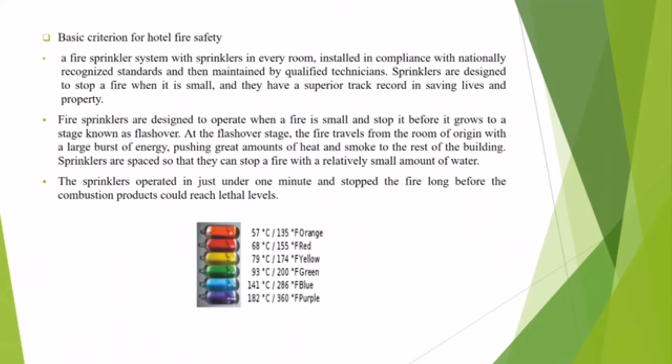Basic criterion for hotel fire safety. A fire sprinkler system with sprinklers in every room, installed in compliance with nationally recognized standards and then maintained by qualified technicians. Sprinklers are designed to stop a fire when it is small, and they have a superior track record in saving life and property.